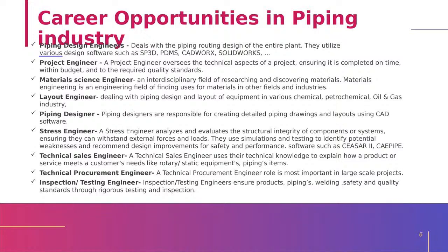Everything will be taken care of by the piping designer. They will mostly be dealing with 2D and AutoPLANT 3D. Next role is stress engineer. A stress engineer's role is to evaluate the structural integrity of the entire piping system, considering the external loads and the forces acting on any piping and connected equipment. The software we mostly use for this stress analysis is CAESAR II and CEPIPE. He plays a major role along with the piping engineer.